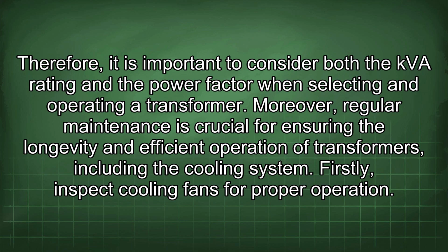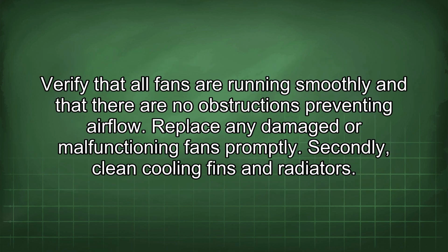Moreover, regular maintenance is crucial for ensuring the longevity and efficient operation of transformers, including the cooling system. Firstly, inspect cooling fans for proper operation. Verify that all fans are running smoothly and that there are no obstructions preventing airflow. Replace any damaged or malfunctioning fans promptly.